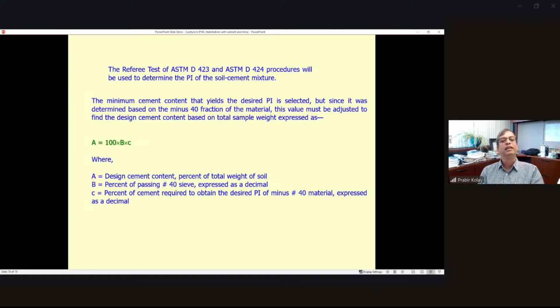For the durability aspect, you prepare a sample and then you do accelerated freezing and thawing, or wetting and drying, and see what is happening. Basically, you need to see the volume change and the loss of mass, all these things you need to check, and after how many repeated cycles, and then you can determine. So you cannot just say it. You need to do the test, and only then can you say how durable it is.